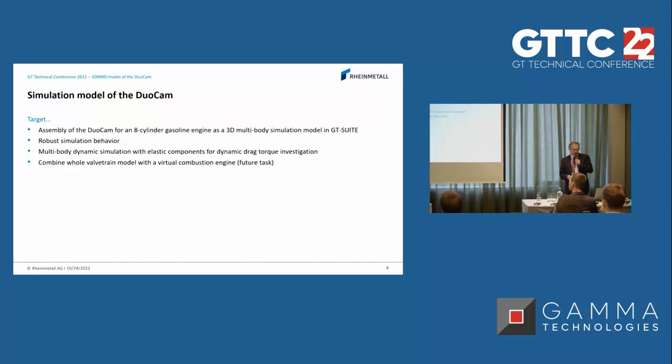The model is used for multi-body dynamic analysis with elastic components, and we want to investigate the drag torque behavior for the DuoCam. Furthermore, it is possible, of course, to combine the model with a virtual engine to consider the elasticities of the whole valve train to the load change.